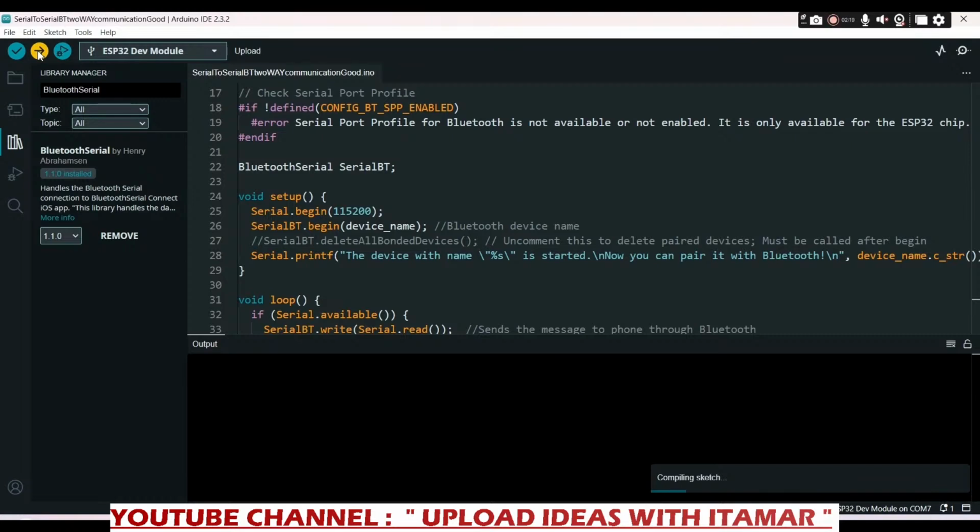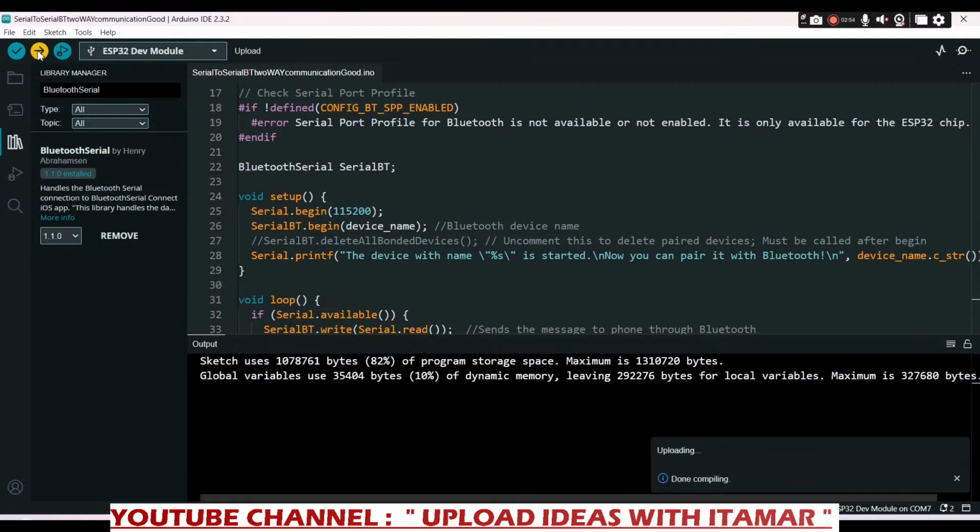Please, while uploading the code, you got to press the boot button if you need. Of course, I think there are versions of the ESP board that don't need you to press the boot button, but as for me, I need to press the boot button to avoid errors.